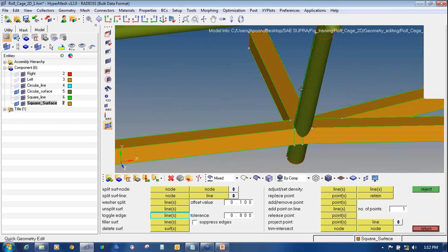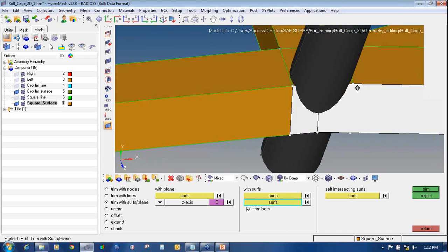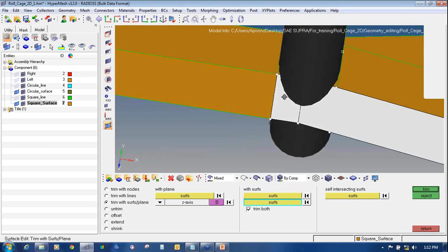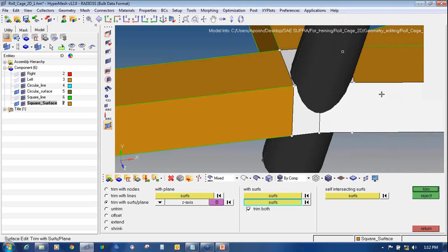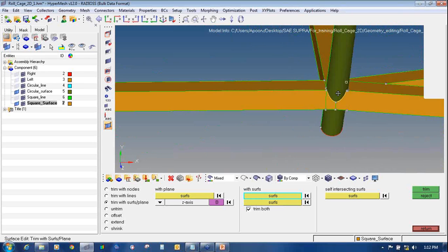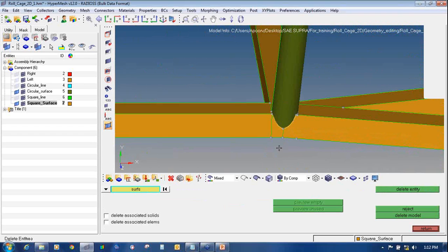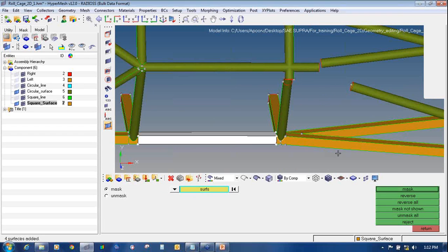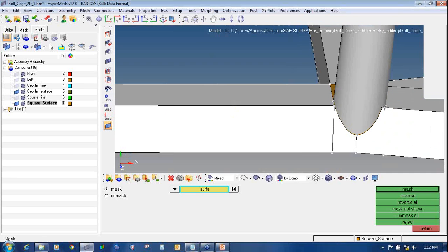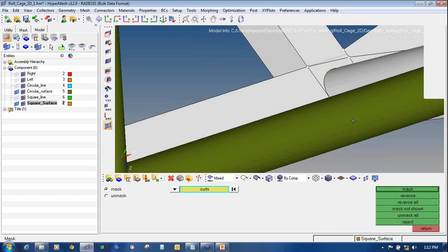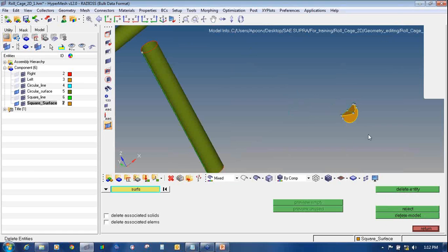Again click unmask all, Shift F9, the last joint. This will get trimmed with only these surfaces. Then click on trim. Go to delete and delete the extended one. Mask panel and mask all the outer surfaces. And delete the inner one.